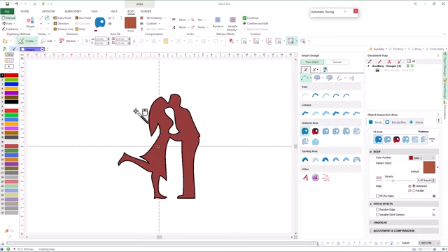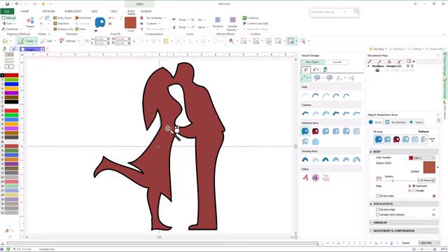Auto trace works as follows. When we click on a point in the image, the tool gets the color at that point and starts scanning the image following a horizontal line from left to right. This process continues until it finds an edge, that is, a significant color difference with respect to the color of the point where we clicked. It then marks that point as the start point and begins to navigate the image along that edge, keeping track of the path it is following. It stops when it returns to the marked starting point. Immediately, it presents a preview of the contour it has detected.